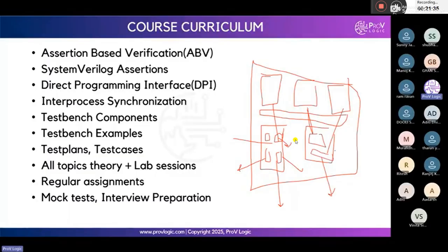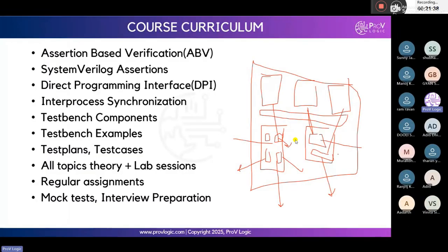In this subsystem, there are two different IPs. One IP is related to the Wi-Fi module, the second IP is related to the GSM module. The processor has n number of cores. Whenever we are doing verification, we need to come from the low level. First we verify the IP, and once all functionality is working properly and verified, then we connect at the subsystem level, and then at the SoC level. I think everyone understood the difference between IP level verification and SoC level verification. And we also have formal verification and functional verification.